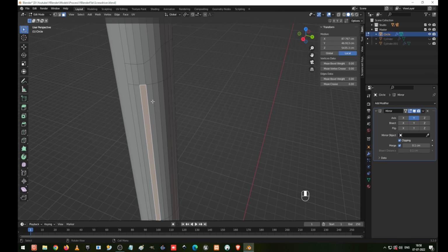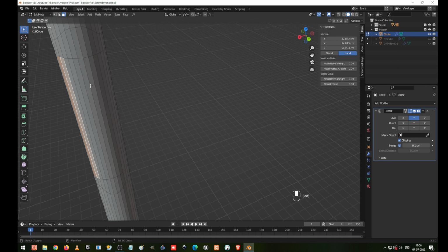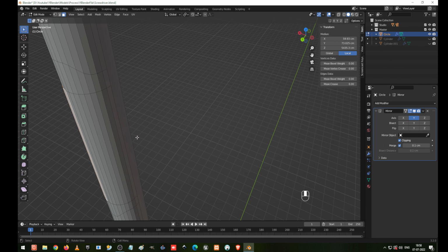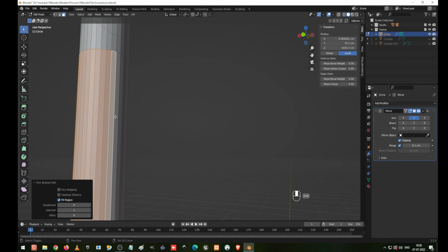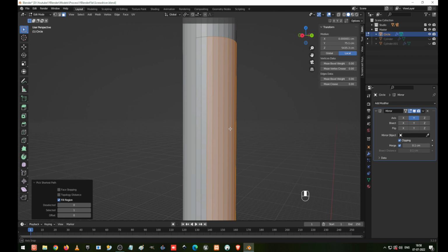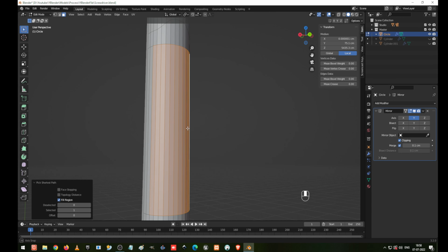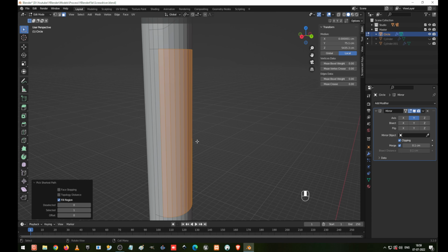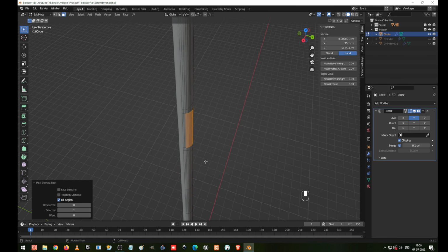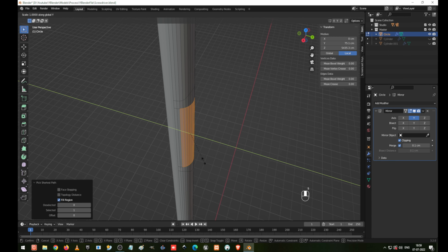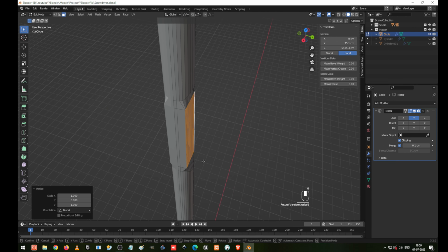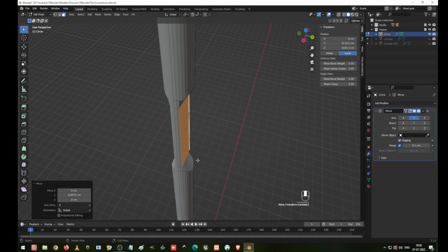and I'm going to leave these two. Okay, fine, so this, let it be 2. So I'm going to select up to here. So now I have left 2 sections, and I have selected the other faces. Now after doing this, I press scale it in Y axis 0, enter, and G Y to move towards the scene.